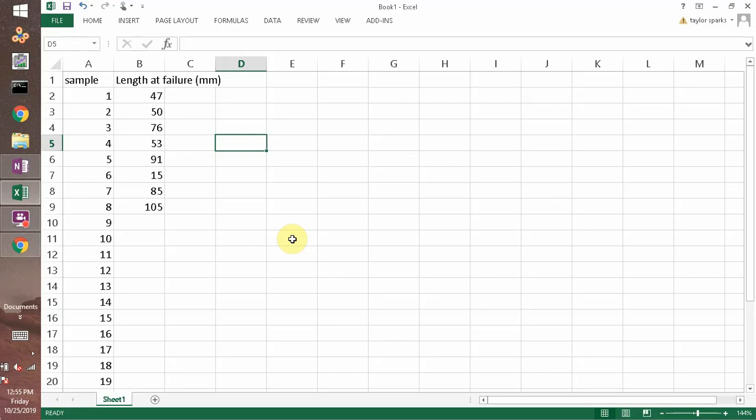And here's the numbers we got. Now, ostensibly, these all came from the same baggie, so they'd be the same. In reality, they look like there's some variety in processing. But this is the numbers you see. In the 9 samples that they were able to break, because some they just couldn't break, you see that they stretched anywhere from 15 millimeters up to 105 millimeters, right?